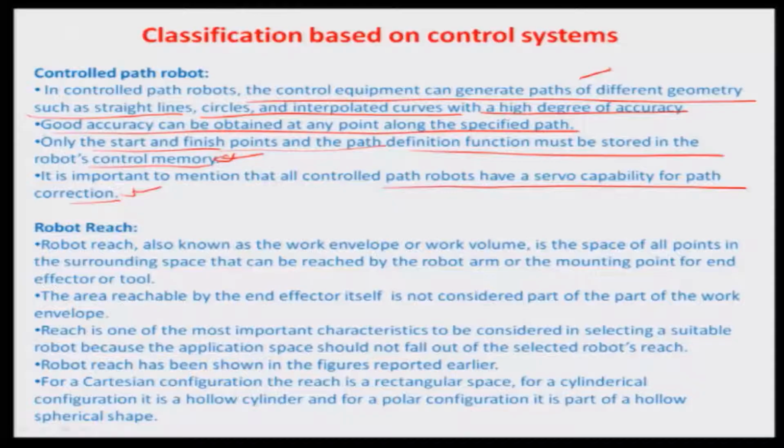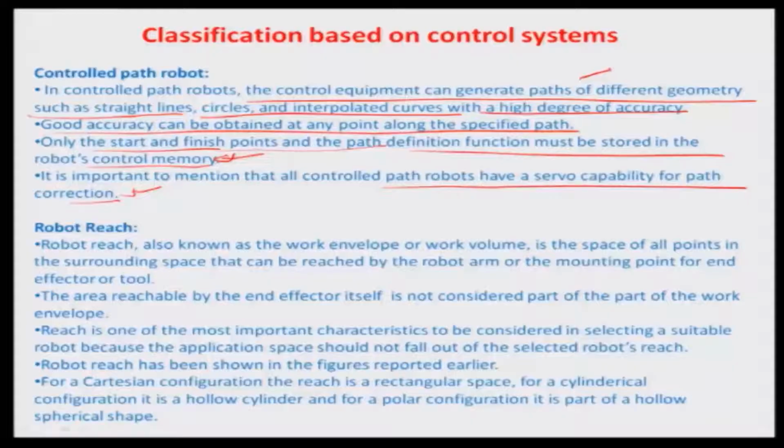So there is a relationship which is available algebraically, in which some computational first-hand activity is carried out by the robot controller itself. The question there is good accuracy, by means of looking at the resolutions of the various stages, looking at the controller resolution to map the data, and so on. That defines the resolution, the least count of motion, on a certain guided path or a controlled path as given by a relationship.